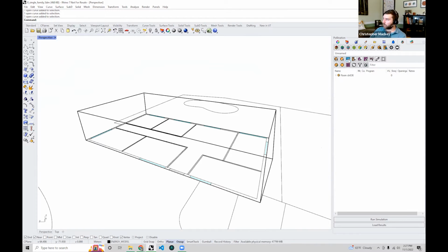So if you left click on add apertures, you'll see again, just like rooms, there are a few different ways of adding apertures to a model. You can select geometries, which we'll go through in a second. You could add apertures by a window to wall ratio. Actually, why don't I show you this right now? Because this is often a very useful feature in early design when you don't have any windows yet.